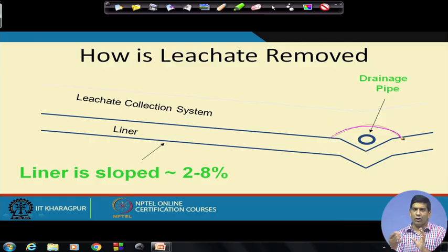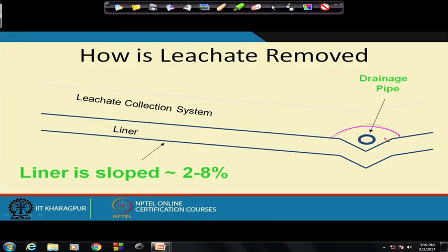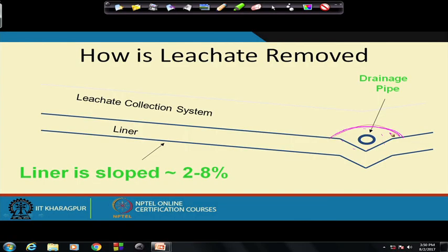It only lets the moisture come in, only lets the water come in, not any of the gluey kind of material with the leachate, otherwise it will clog the pipe. And then you have this sand here, which prevents clogging from the waste coming into these pipes. And this is wrapped around, and I'll show you some pictures of that as well.